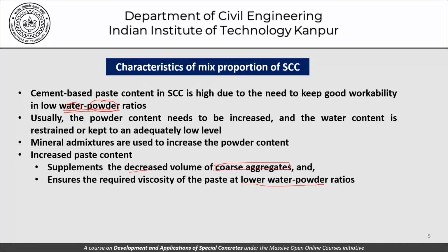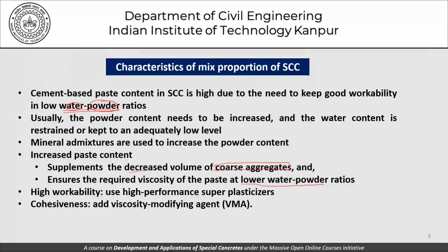So if we increase the powder content, the viscosity or the segregation resistance of that paste increases. High workability is also achieved through using high performance superplasticizers, and we get cohesiveness from using the viscosity modifying agents. We've possibly talked about this earlier, that as far as self-compacting concretes are concerned, we have two important routes.